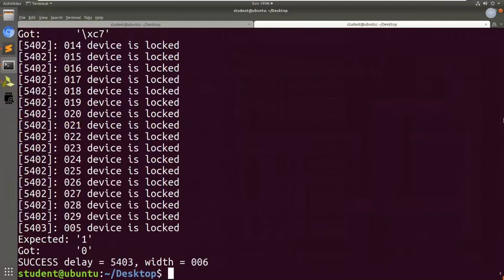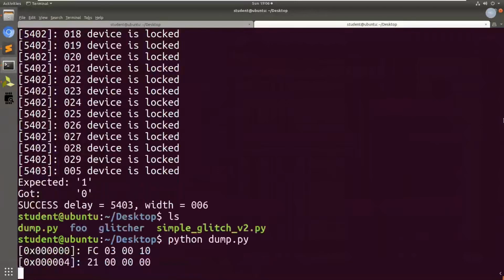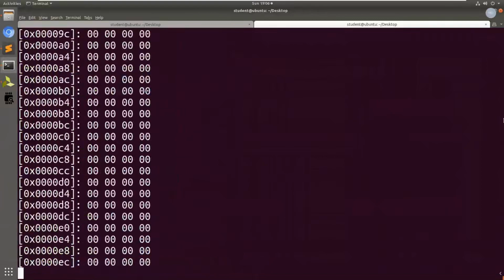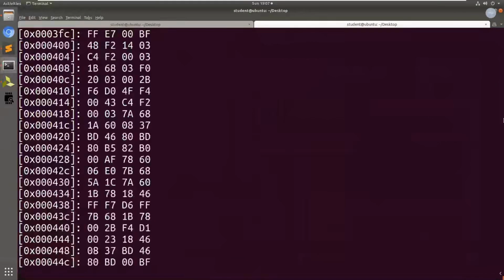So if I was to connect over Picocom right now, I could do R04. Fortunately, I also have a script. It's called dump.py. This is just a script which converts the UU encoded data and lets us dump the binary that's on there. So I'm going to run it, and you can see we're dumping the binary. It's working. So we've succeeded to boot the chip in such a mode where we've defeated its security, and now we're able to pull the firmware off of there.